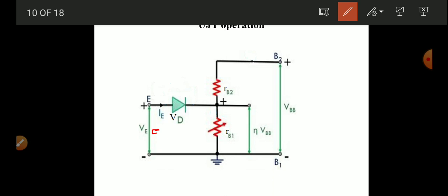This is a regenerative process, and this process is called conductivity modulation because this action happens cumulatively. When the diode becomes on, the holes move from the P region to the N region, the resistance decreases, conductivity increases and the voltage drop decreases.